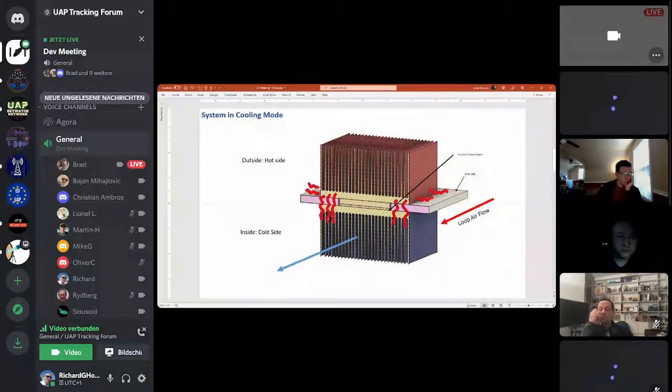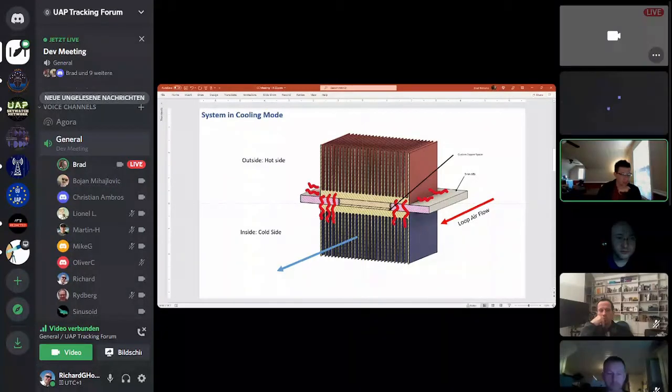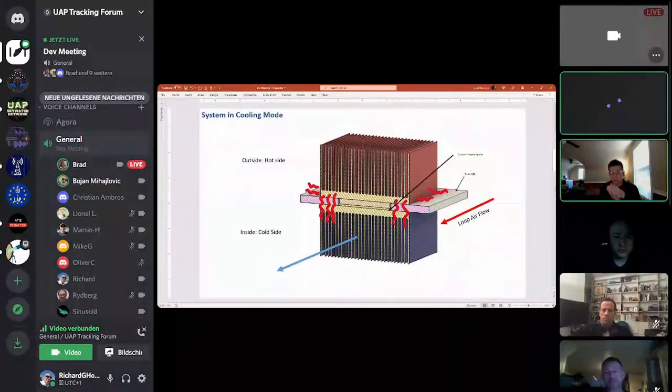Peltier in the middle, there is this custom standoff piece of copper that we would have to source to clear this gap if we mounted it directly to the 5mm ABS. But you can see the problem with a large cold side heat sink is it can easily get contaminated from heat just conducting through the ABS material. This heat sink is going to get very hot. So if those heat sinks are touching ABS, there's going to be a lot of heat transfer between the two, and it's going to cut down the efficiency of the system.